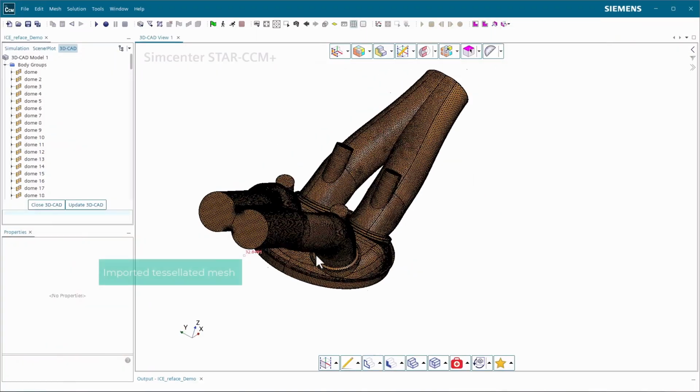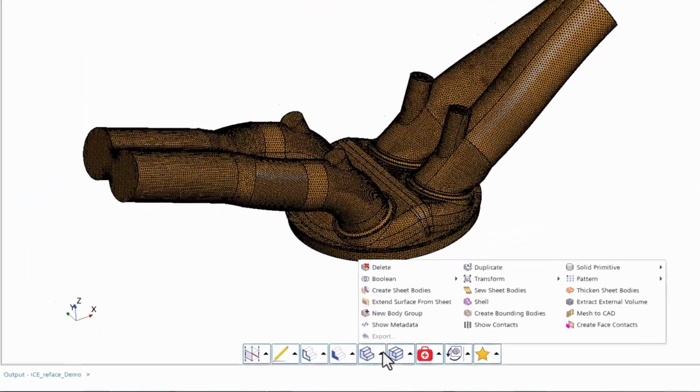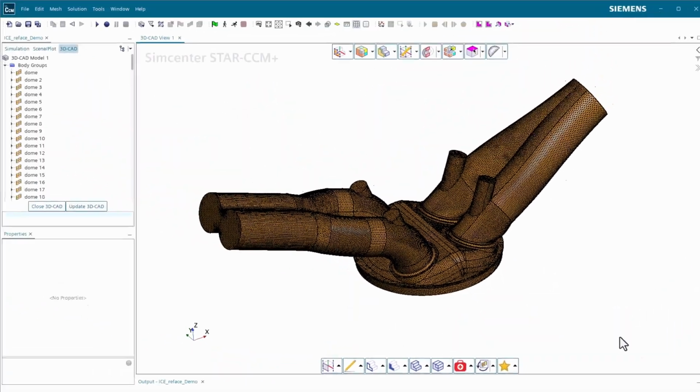Well, there are many benefits to this conversion to CAD bodies. I'll try and give a few examples here. In the first instance, let's say the CFD analyst might not have access to the CAD geometry and is only supplied with a tessellated mesh as a starting point. This is actually quite common for some in-cylinder simulations and the workflows that they use in this vertical. In some cases, that's acceptable. However, the geometry might possess certain elements that are not necessary for the CFD analysis.